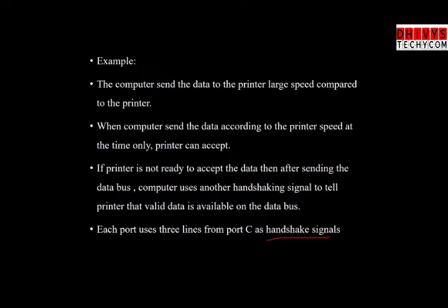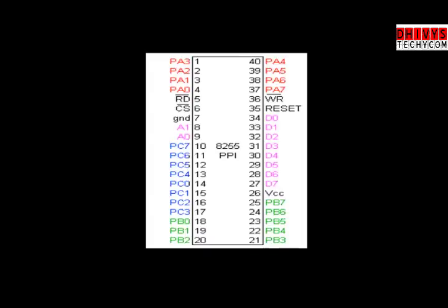So this is a beautiful diagram that represents the pin details of 8255. It is very simple. You'll have port A, which is also a group, and then port B being represented in the color green. This is yet another group, and you'll have port C pins being highlighted, and all these data pins, through which you can conclude that it can access 8 bits of data. And whatever IC you choose, it is important that it has a reset button, because it may have been dumped with unwanted data. It has to be reset for operating in the current situation.